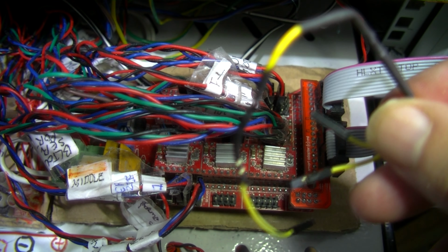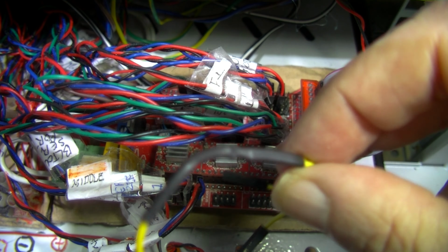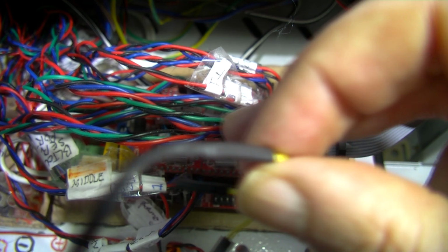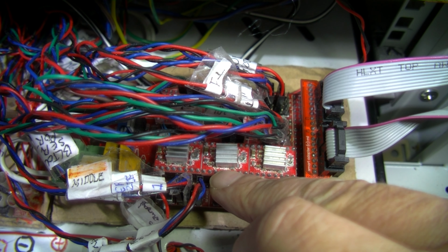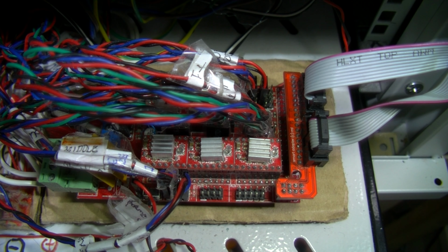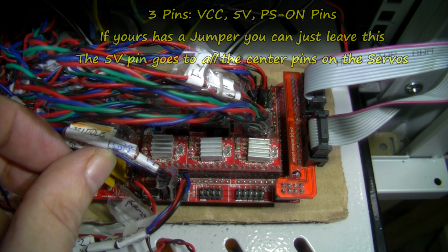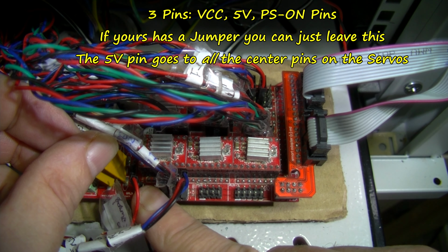And I'm going to plug that into pin 44, and it also has to plug into a 5 volt. That's for my servos and my BL touch, and my filament runout. So I've got those 3 things on those ports. So if I move these wires over a bit, here's a 5 volt pin down here.